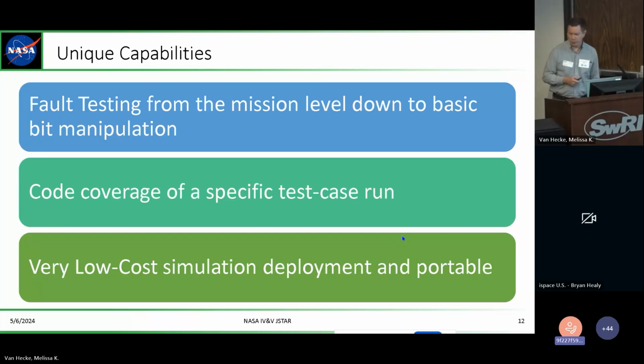Just as an example, we can do code coverage. We can run a mission through, collect the data, and run that through tools that highlight all the code that was run in green. So if I want to run an abort scenario, I can ask what code was actually running for it. I can look at that software and see what of the C++ was actually executed.